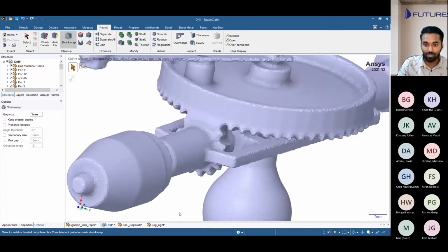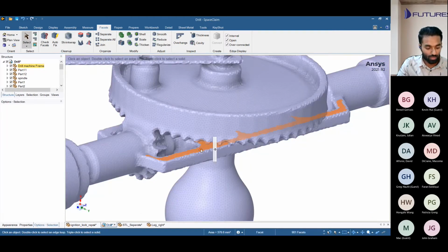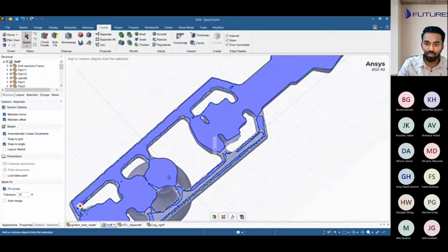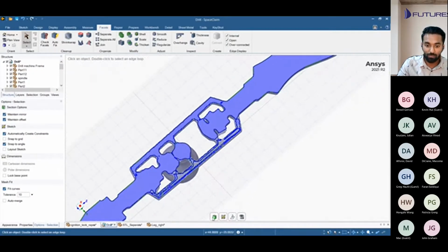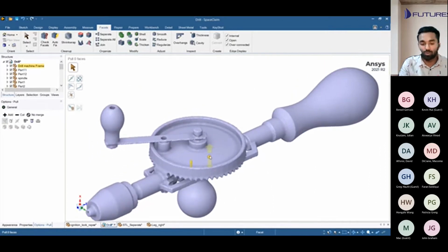As you can see now, it has been converted into STL. And if I now go to the cross sections, all of the parts have been merged. That means I can just go ahead and put it into a slicing software or the software of the printer and print it in one go.